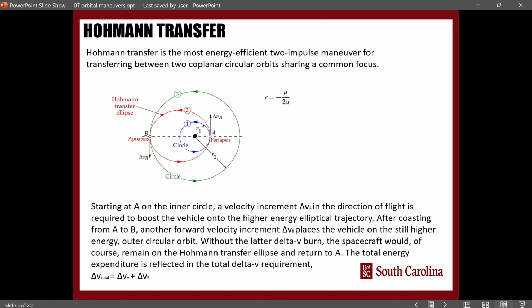So the velocity you need to add is just in the tangential direction, right? And there is no direction change. You just have to change the magnitude of velocity at that instant, right? Because the direction at the periapsis for both and apoapsis for both orbits is going to be the same direction, right? Does that make sense?